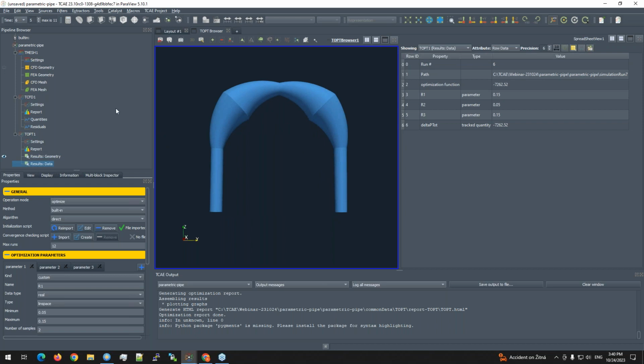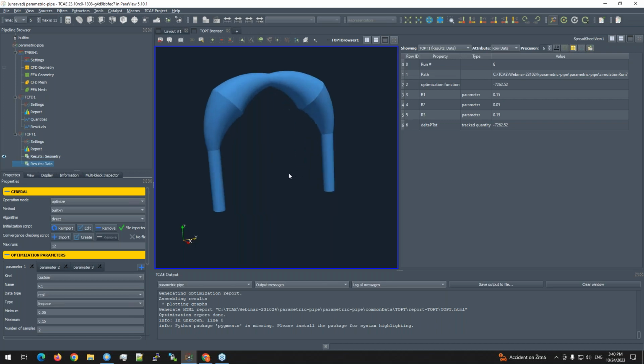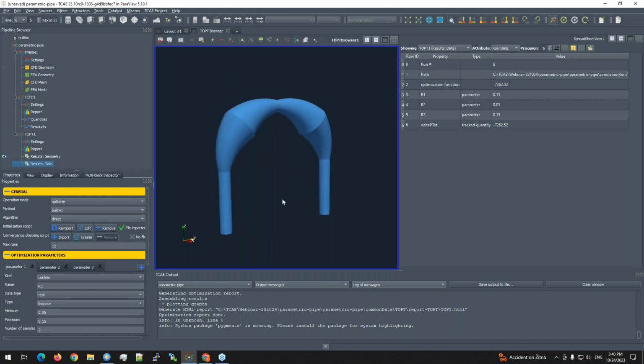Okay, and typically what we do, if you run hundreds of simulations, we would like to have a not super fine mesh, or we need to also optimize the mesh parameters. Even though we know that the accuracy is lower, we are short on time, and we would like to simulate 1,000 iterations, for example, or optimization loops within a few weeks, depending on the size of the problem.